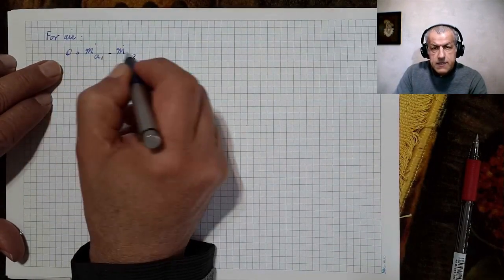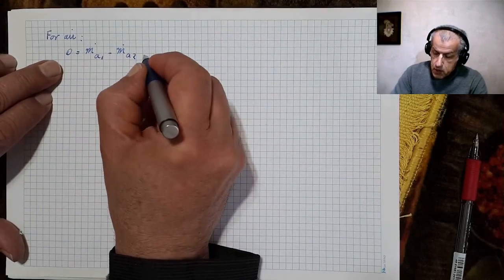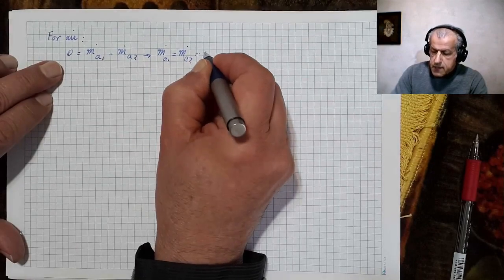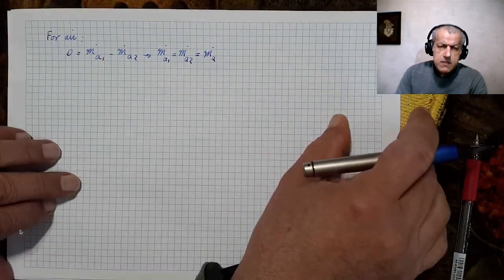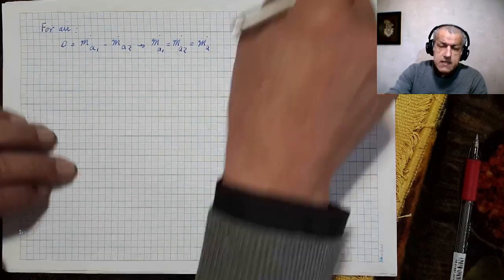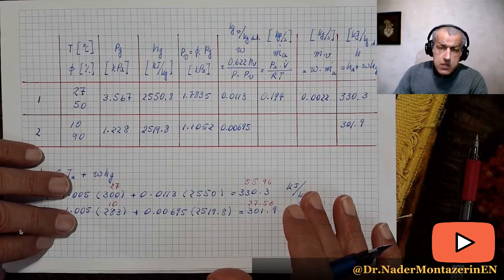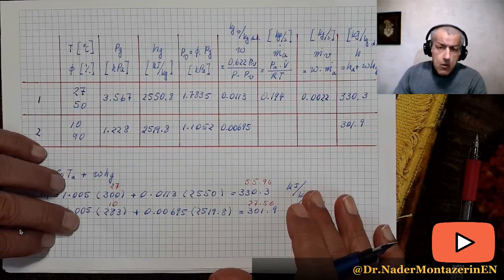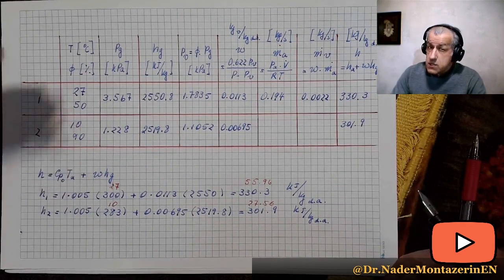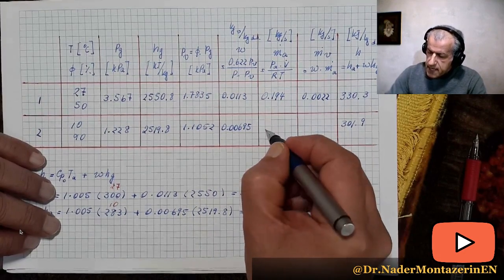And this is the m sub i, this is m sub e, and therefore what we conclude from this equation is that m dot A1 equals m dot A2, and that equals m dot A. Of course, it is pretty evident at this stage for every student, but I would just insist to use this equation and make it a conclusion, just to make sure that we all remember the old process of drawing such conclusions, that incoming mass and outgoing mass are equal, just drawing such conclusion from our equation and from the mass conservation law. So if m dot A is the same, this would be